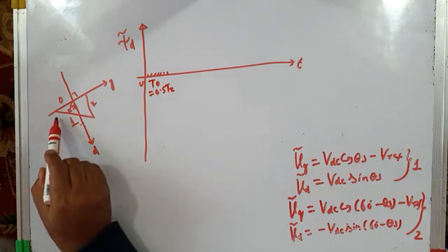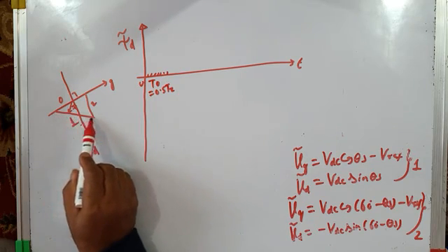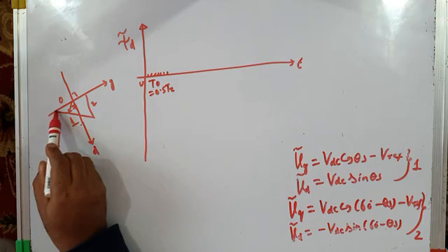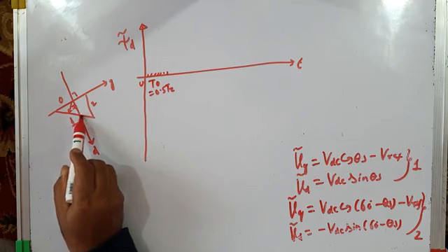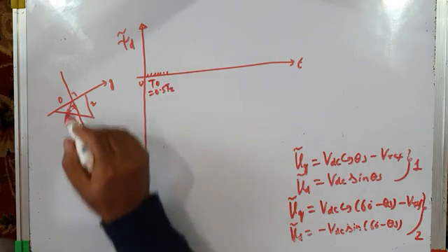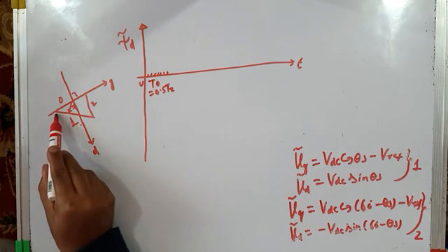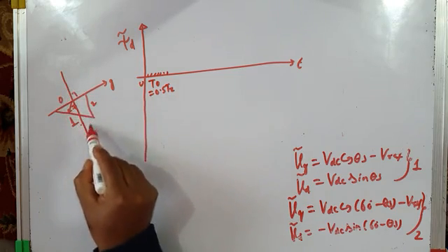and then we apply active vector 1. You can very clearly see when active vector 1 is applied, the stator flux ripple vector, which was maximum negative here, becomes less negative now, and here it becomes 0, and then it grows in the positive direction. So along d-axis, its d-axis component starts from 0 and then increases along d-axis like this.